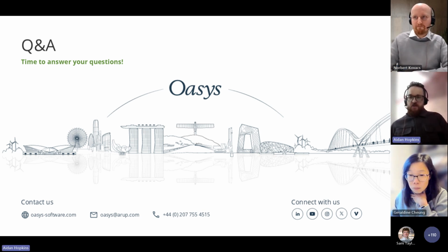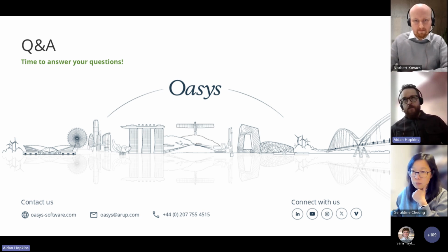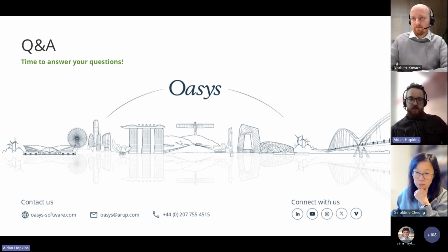Yeah, I think the question is looking at whether we modeled it by ring. Now, in this case, we went pretty close to what the actual TBM ring length would be, just to capture each advance. I would say that the length is really up to you. It's not something that's determined in XDisp. So if you want to do longer sections to reduce the number of computations, that's totally appropriate.